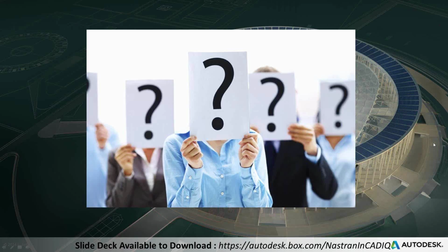We do have a question. Do you have to set up contacts for the automatic method? Nope, they are automatically set up, which is yet a further advantage of using the automatic method. So I'm assuming, because you said it defaults to separation, correct? Yeah, on the automatic method, it's always separation. And actually, if you're doing impact, you probably want to do that anyway.